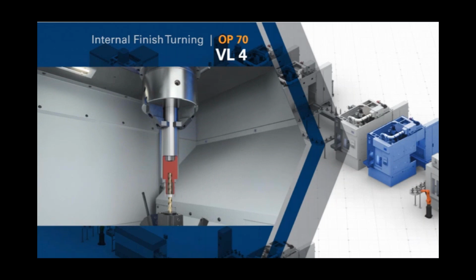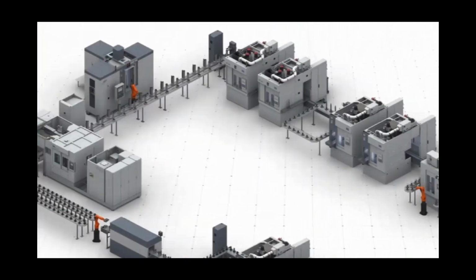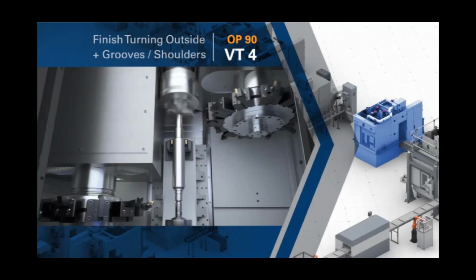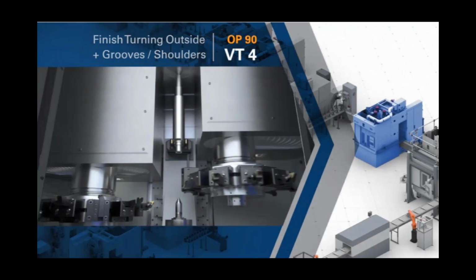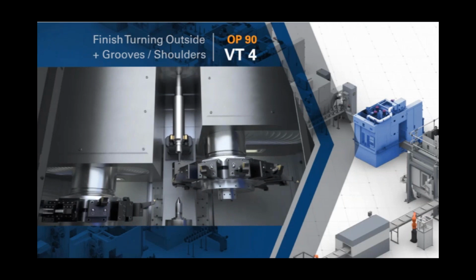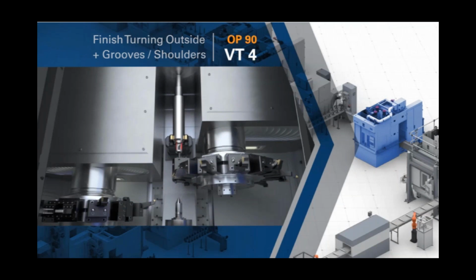So we've gone on to a couple of VL4s here for the internal finish machining. We passed over internal gear cutting, and now we're doing finish OD work with a little bit of ID work in there. And then the finish operation is going to be on a VTC250DS, again, a mouthful, where we are doing the finish grinding.